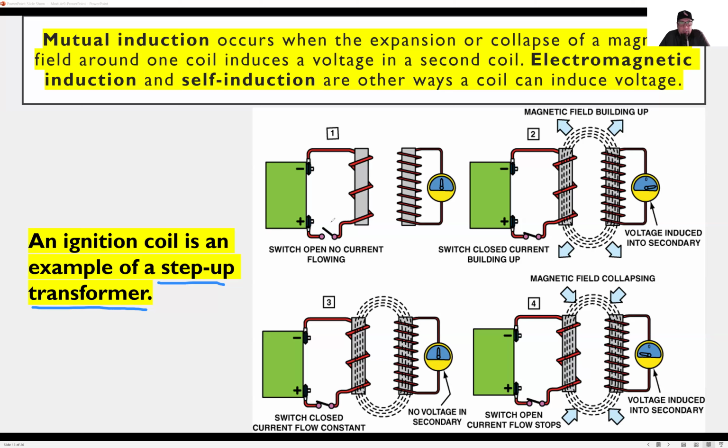So low voltage in the battery, we always have 12 volts in our normal automotive batteries, right? With the engine on idling, it's roughly 13 and a half to 15. But we have 12 volts in our battery. But our ignition coils, if anyone knows anything about ignition coils, I don't expect anyone to in this class, ignition coils require a lot more voltage than 12. They require somewhere in the thousands. I would say 10,000 to maybe as high as 60,000, maybe even higher, depending if they're towing something or if you're going up a hill or you're racing. The higher the load on the engine, the more voltage it'll need. So we're talking thousands of volts.